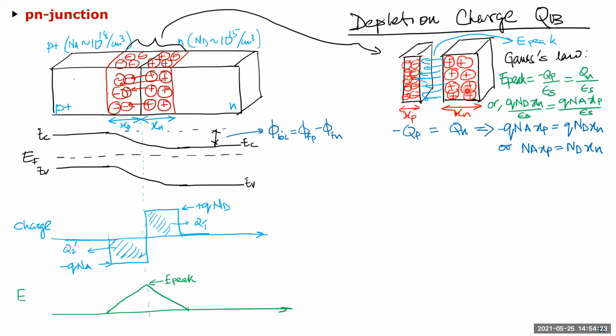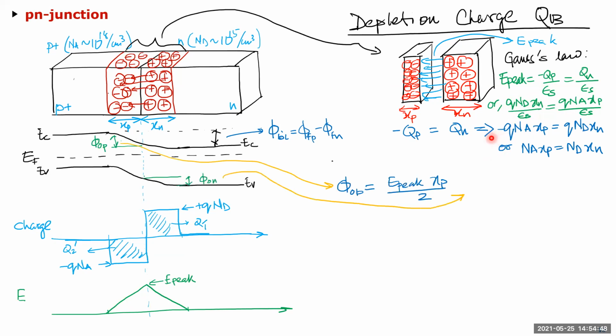In this case it's silicon, so it's the permittivity of the material, which is about 12 times that of free space, right? So then you substitute this equation here. It's Q times the donor concentration times the length of the depletion region divided by epsilon S is equal to this, and so on. So that's the expression, and I'll show you why we're using that expression.